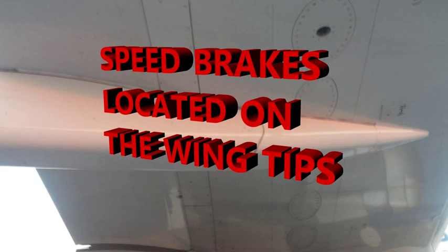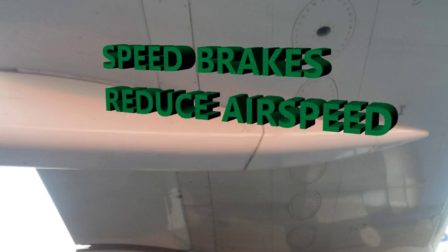Speed brakes are, again, for creating drag. But this has to do mostly with speed. That's why they're called speed brakes, because they're slowing down the plane, reducing the airspeed. They really don't affect the lift. Just think about those affecting airspeed. As a result, they're increasing the drag, as well as increasing the angle of approach during the landing phase. Okay, where are the speed brakes located? These are located on the bottom of the wing's trailing edges. That's where you'll find those.